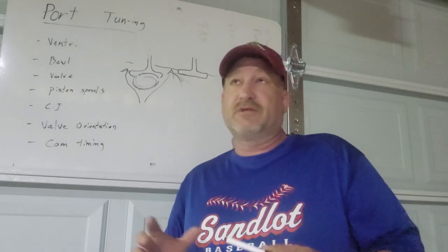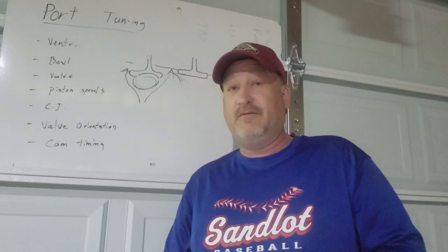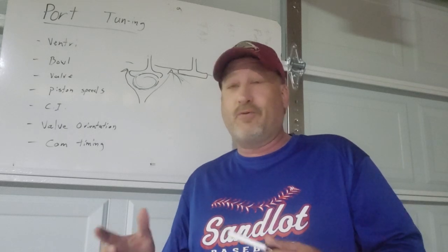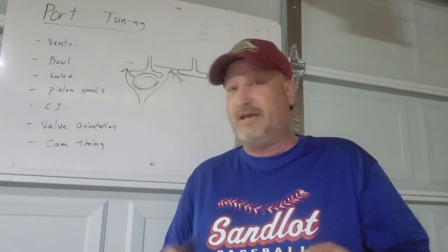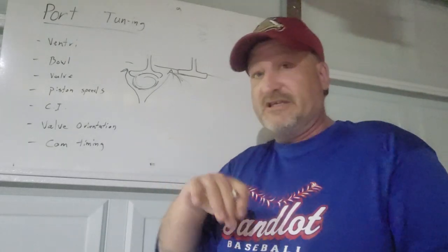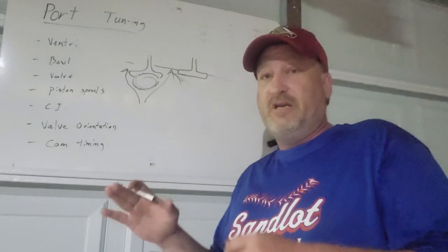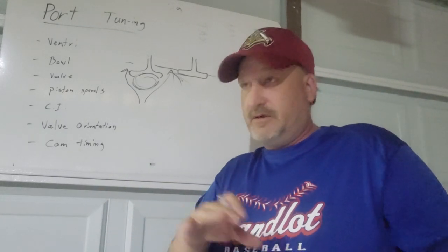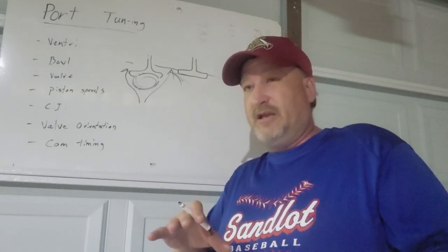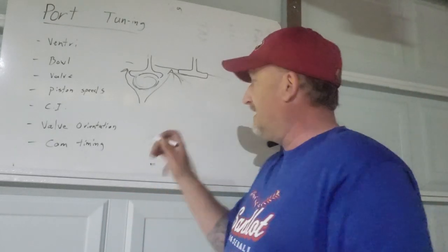The Oldsmobile was a little bit more specific to when and how they approach the port tuning of the intake. I'm just going to talk about the intake at this point. Now, I'm going to draw just the short-turn radius or the port floor between a small block Chevy, small block Chrysler, compared to even some of the small block Fords or the Oldsmobile or Pontiac designs.